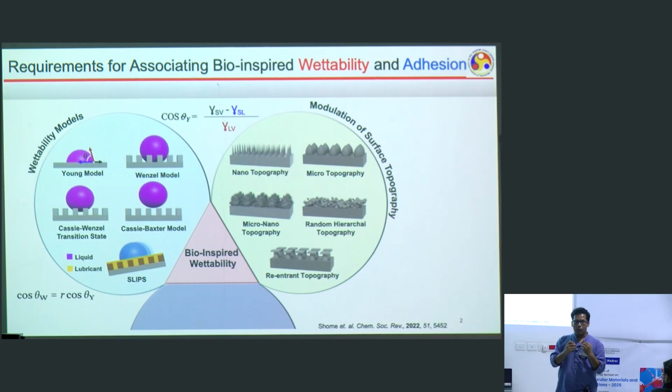Okay, this wettability cannot be explained based on Young and Wenzel. You cannot really find any roughness factor that explains this, because it crosses this cosine limit. This roughness factor will always be more than 1, right? So it's not theoretically possible to explain a contact angle as high as above 150 with this Wenzel model, and forget about the Young angle.